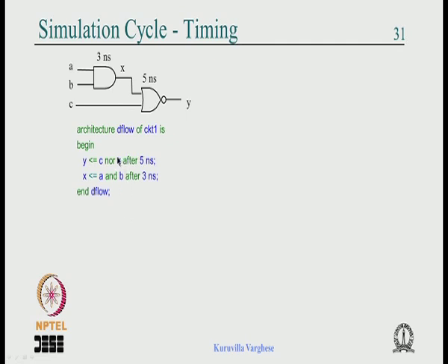It will look where X happens and compute the Y, and that will happen after 103 plus 5 nanosecond. Again it looks if there is anything remaining to be computed for 103 nanosecond, and proceeds to the next simulation time, 108 nanosecond, and so on, okay. That is how the simulator resolves the concurrency.